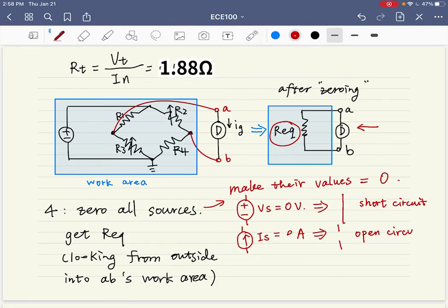And as you see here, what should we do? Yeah, by zeroing the voltage source, we are connecting it with a wire directly, right? And what is the result? Yes, if we name this node as 3 and this node as 4, we'll see that after we zero the source, 3 and 4 are equivalent now, right? So let's repeat the analysis about the resistance relationship again.